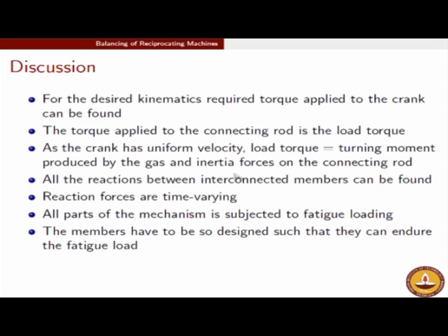So because the crank is moving at a constant angular speed, there has to be a balance between this moment, which is moment m, or the load torque which is applied to the crank, and all other moments due to all other forces. And all these other moments due to all other forces are basically the turning moment.